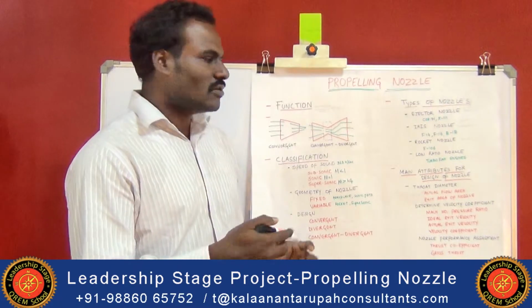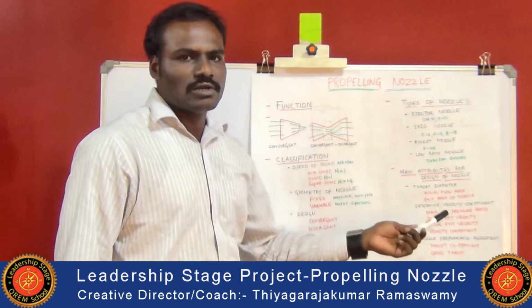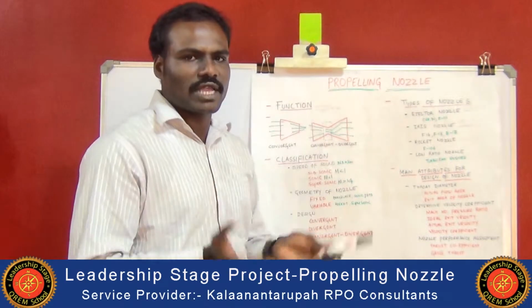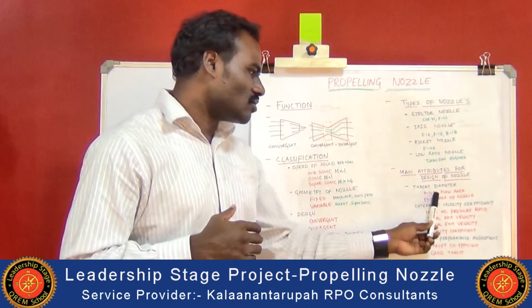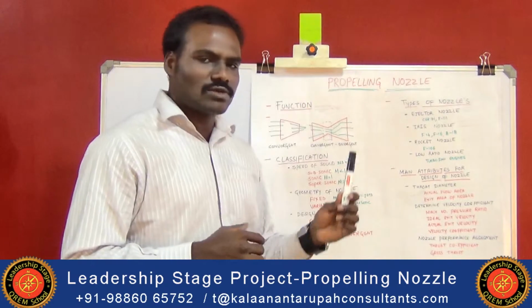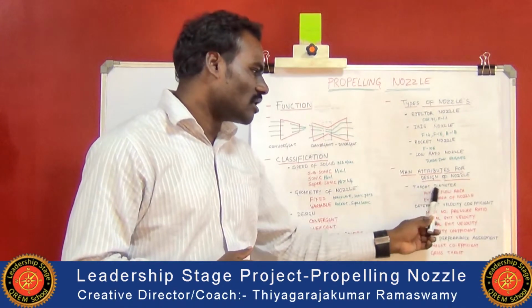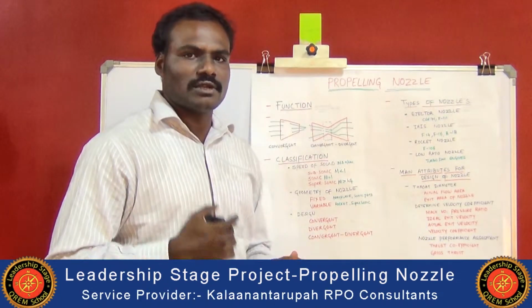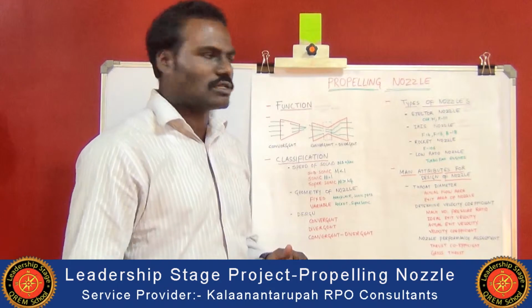With respect to this, we are calculating the actual flow area needed from the actual area available. With respect to the actual available area as well as the actual flow area, we are calculating the exit area of the nozzle. With respect to these values, we are calculating the throat diameter, which helps us in determining the diameter of the throat as well as the diameter of the nozzle.